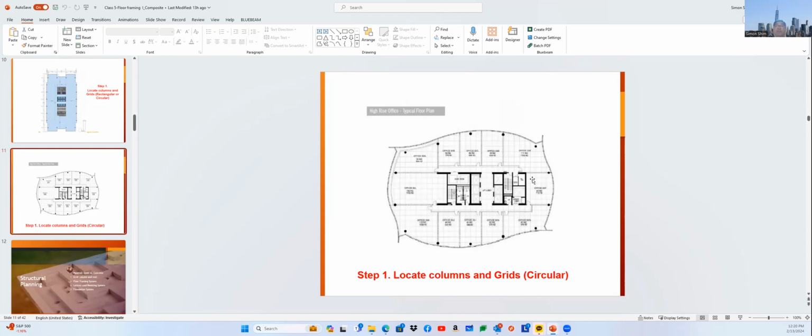All right, one more similar example, with 2 stairs and elevators. But this building has a curved lower plate, and the columns are all placed along the exterior face. You need to always keep an eye on that. This is the span, column to wall, vertical support, and those span lengths.